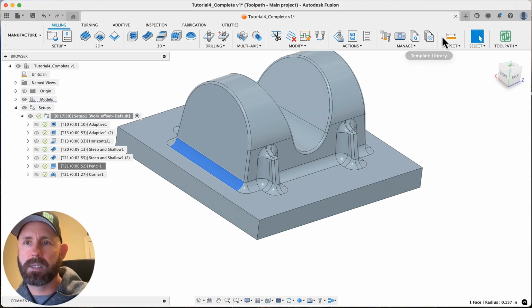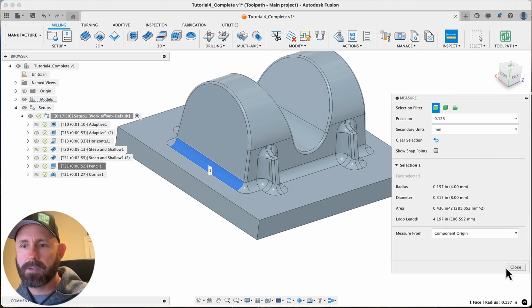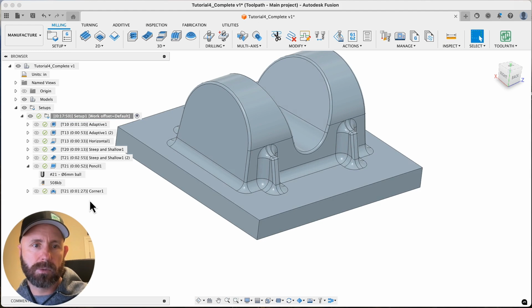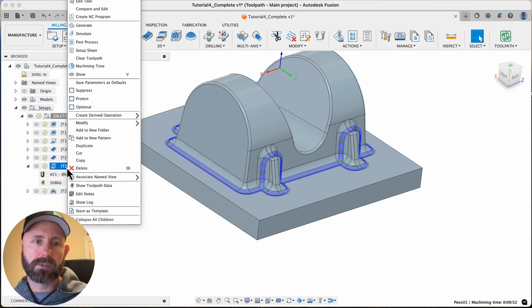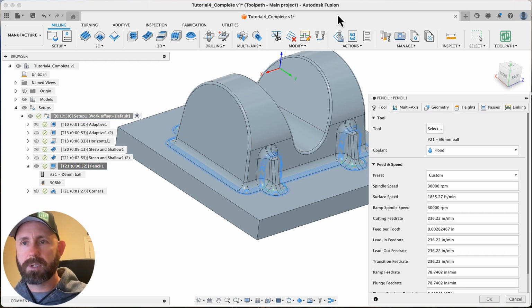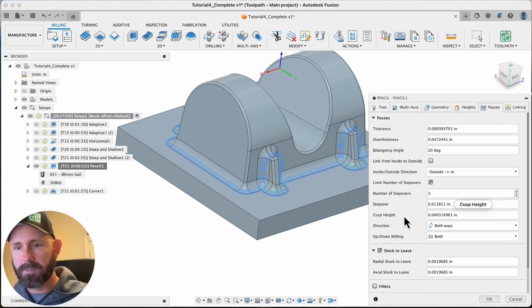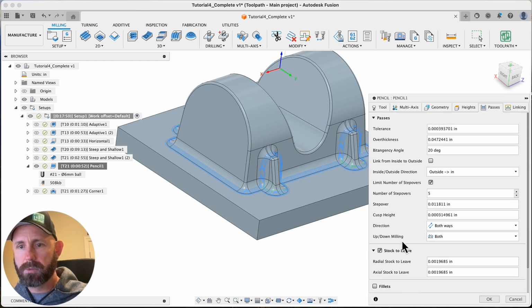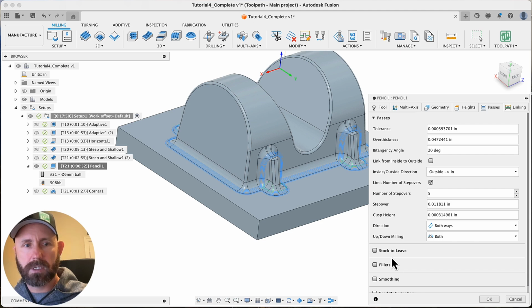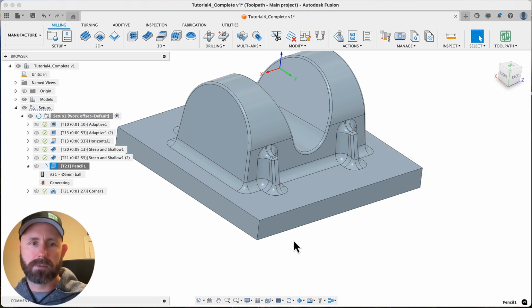this fillet is 8 millimeters. This tool is 6. So in the over thickness, you would want to say I have at least two millimeters of over thickness, and it'll go find that fillet. So just a quick little tip. I'm running along again. I could talk CAM all day. If we went to, yeah, I'm going to turn that off. Let's make sure we get the result that we expected.